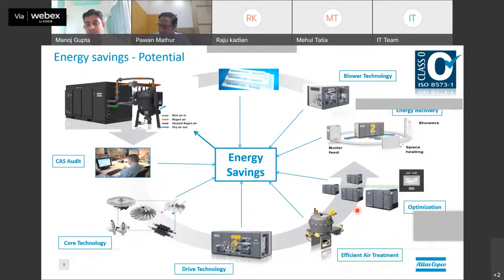Now the optimization, where multiple compressors are there. If we have the facility with the controller, we can reduce the pressure band. When multiple compressors are there, normally they will run one by one, then two, then three, then four, in sequence. By doing this sequence, we have a huge pressure drop, because we have to increase the pressure band. So to optimize that, we can reduce the pressure band, and we can propose the most energy efficient combination of solutions, which can deliver the set, desired required pressure.